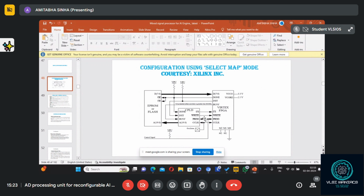Once the write bar signal is low, some data will be downloaded. But what data? That's why it will send the address to the memory. Now how will it get to know what address? Because the CPU has already sent the command to download. Along with that command, it must have sent the starting address and how many bytes are to be transferred.